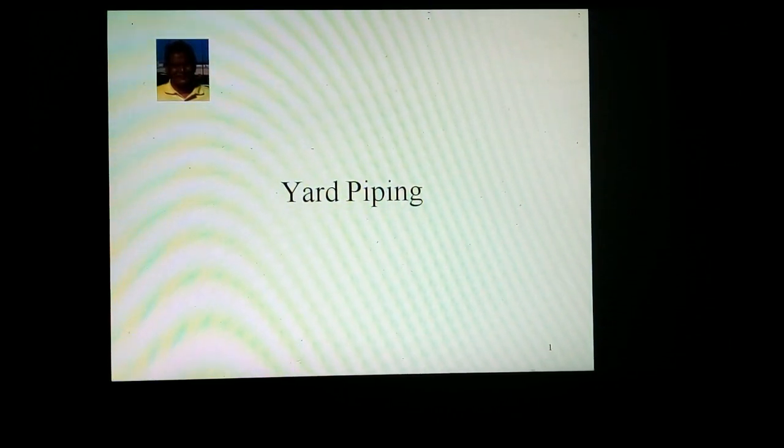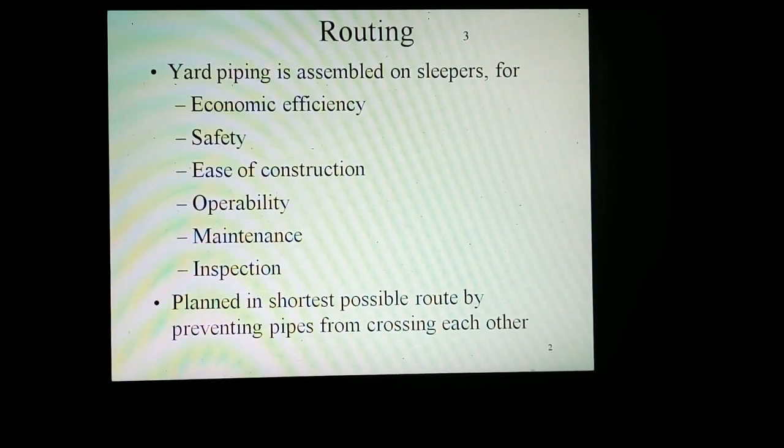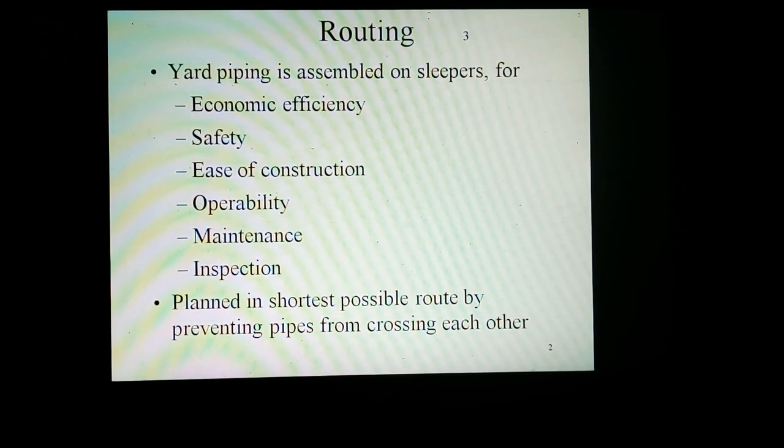This video is about yard piping routing. Basically, yard piping is desirable to be assembled in one area on sleepers for economic efficiency, safety, ease of construction, operability, and maintenance and inspection, and to be planned in the shortest possible route, also preventing pipes from crossing each other.